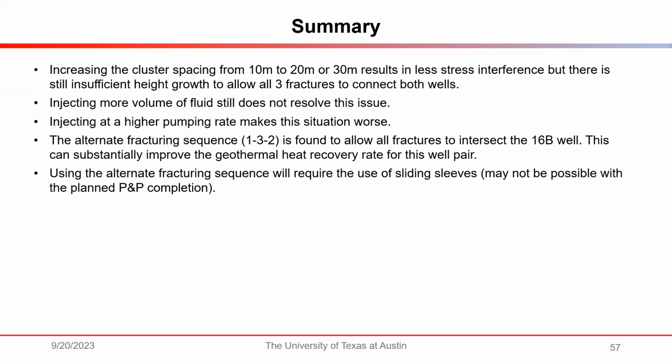That makes sense. In other words, if you were to reduce the slot width by a factor of 2, let's say, which is what you said you did, then of course you'd get much larger viscous pressure drops in the fracture, and that would give you more intersections. The impact of the stress shadow would be reduced as a result of that, for sure. Yeah, that makes sense.